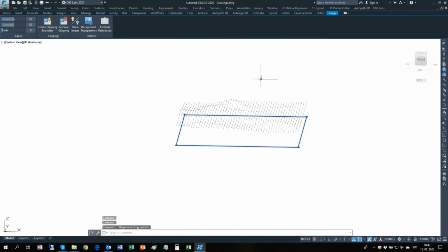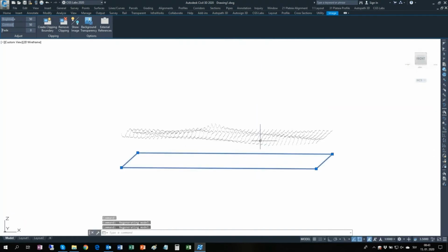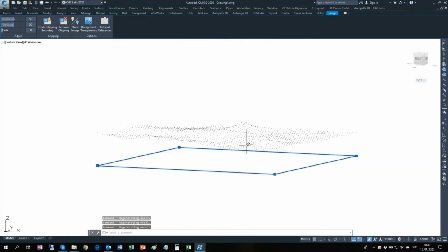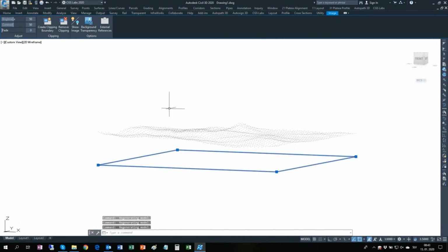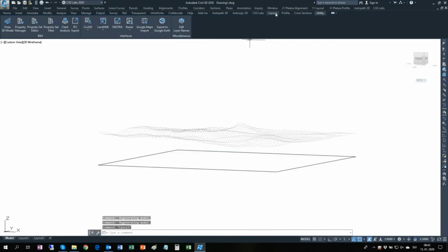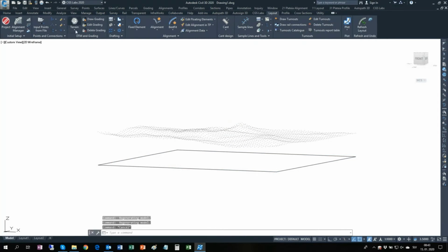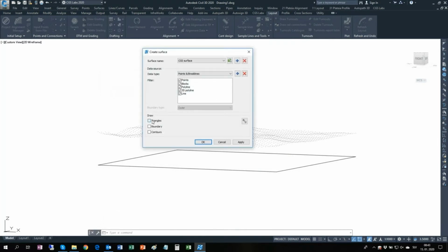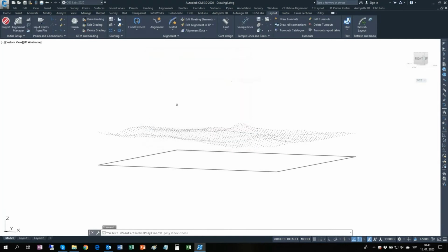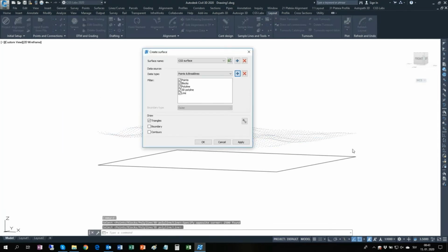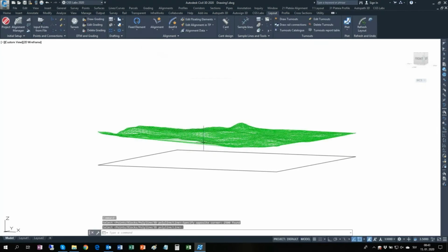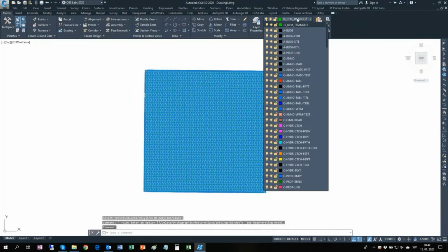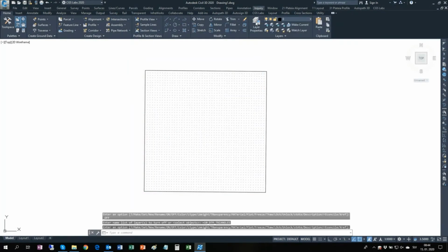Here we have the elevation data that have been imported for the selected area. And within Ferrovia software, in the layout model, there is a terrain modeling tool. So first we define a surface name. And here we define the input data, either points, blocks, polyline, 3D polyline, or other elements. We have only points here, drawn as triangles in this example as selected. So we have our model already available.